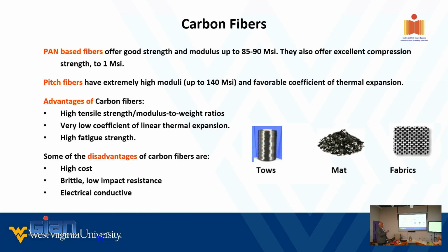But you have low-grade fibers that are only $4 or $5, maybe even a little bit less now. Zoltek produces low-grade fibers. But the beauty of carbon fibers is very high fatigue resistance and low coefficient of linear thermal expansion.